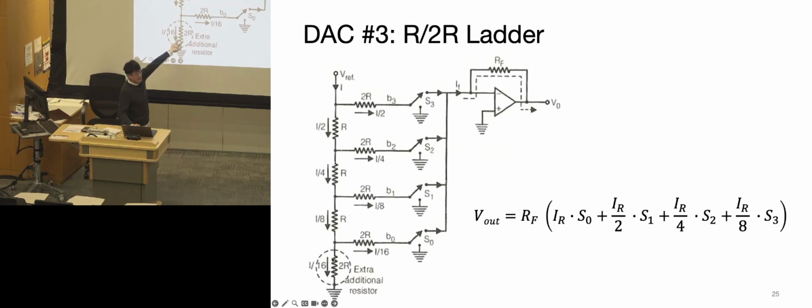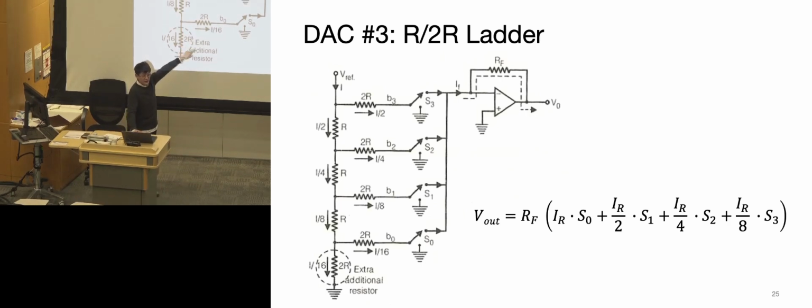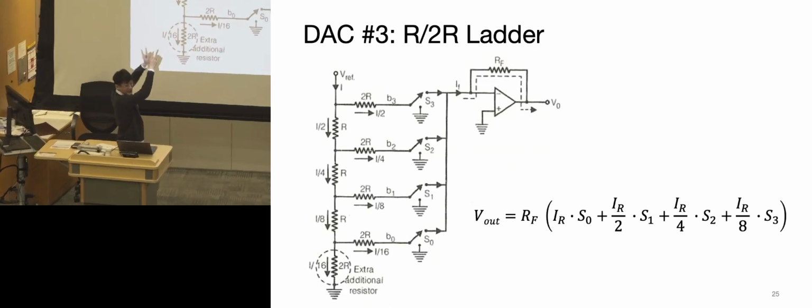So if you just combine them together, these two become an R together, and then plus this 2R, and then another 2R together become R, and then add that. So basically, each of these nodes divides the previous node by half, if that makes sense. Again, these are the voltage dividers that we did before. Essentially these two in parallel, added together, become 1R, and that 1R in series with this R became the 2R. So another 2R in parallel situation, and then just go all the way up.